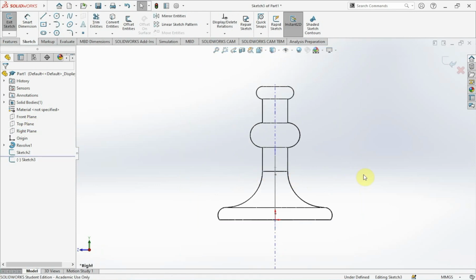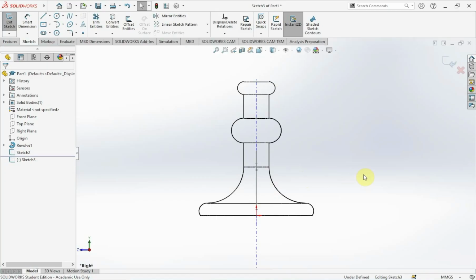Remember, this is another different sketch. So we're going to have two sketches. And the sketch will basically be working on the girth or the width of the sweep. And on the other sketch, it's basically the sweep path or the shape that our sweep is going to take.